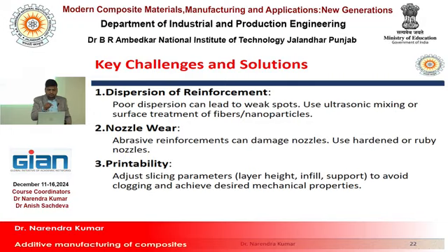So you need to mix the reinforcement and matrix properly by using good mixing mechanisms. Ultrasonic mixing can be used for this purpose. Nozzle wear, you need to take care of this because we have already discussed it. Printability, you need to adjust the parameters, like thickness, height, and support, to avoid clogging or to achieve the desired mechanical properties.